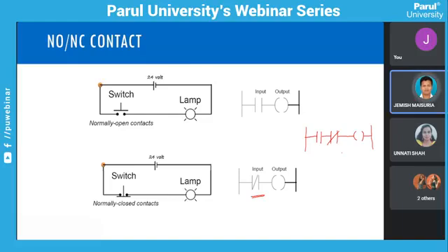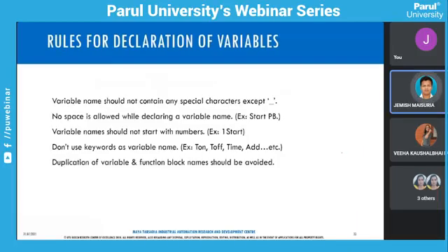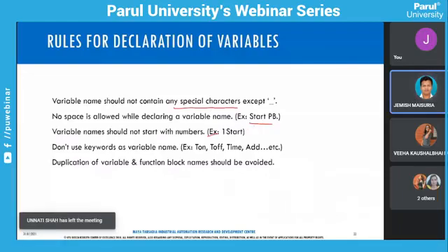this is not the only thing when you do the programming. Some more variables. You can provide names, similar to any programming language; there are different kinds of rules. It must not contain any special characters, and whatever predefined blocks are there, you cannot use, and you cannot use spaces between the variable name. And this is nothing but a predefined name of the block, because when you are going to program a PLC,